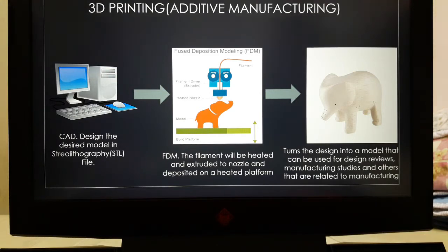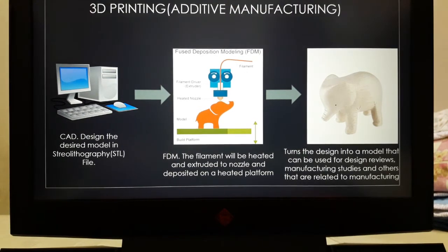subtractive manufacturing. Additive manufacturing is a process in which a 3D object that was designed by CAD is constructed by successively depositing material in layers. As for subtractive manufacturing, the desired 3D object is constructed by removing or cutting the material away from a solid block by using particular machining processes, for example milling or turning. So in this project, the focus is on additive manufacturing, which will fabricate the product.